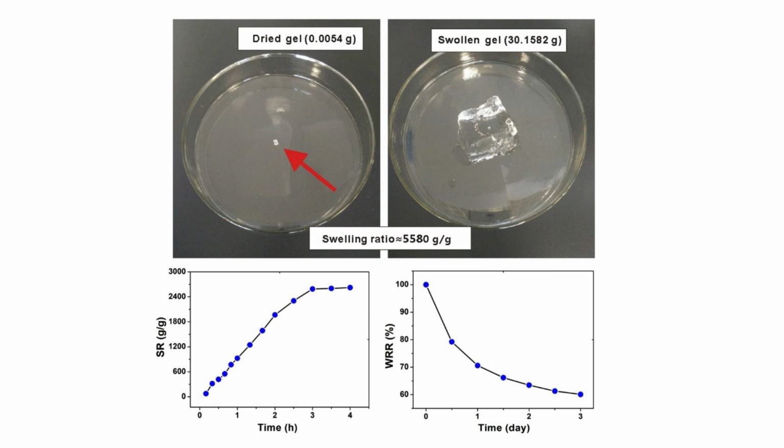In a typical experiment, the sample is submerged in a specific solvent, e.g. xylene, at a controlled, elevated temperature, like 110 degrees Celsius. The sample swells as the solvent penetrates the network, eventually reaching equilibrium, where swelling stops. Finally, the swollen sample is removed.